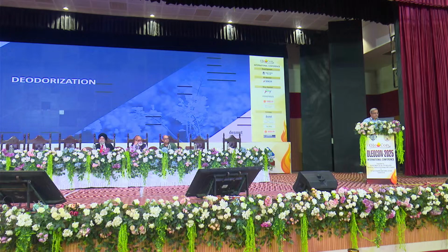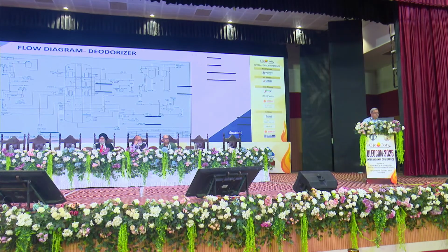Deodorization: a simple deodorization section can be in many configurations, but typically it has the heating tray, the deodorizing trays, the internal heat recovery tray, the scrubber, the deaerator, of course the four-stage vacuum system as we very typically see, and of course the cooling of the deodorized oil.